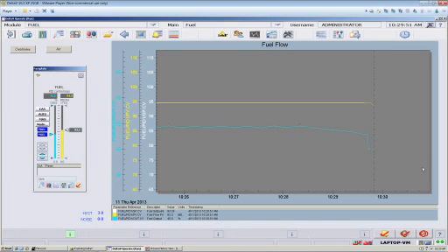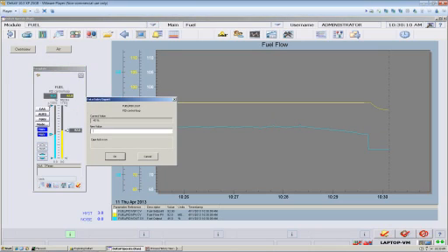Part of this I'll simplify because I know that the hysteresis is 3%. In the real world, you're discovering this. You're not proving it, you're discovering it. But we have some limited time here. What I would normally do is start out with maybe a 0.25% bump. So from 45% to 45.25.